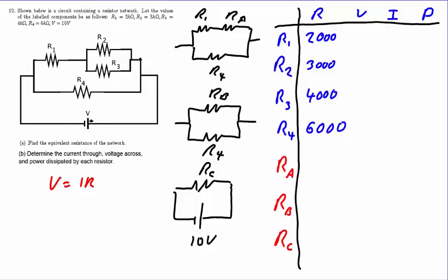If we put 2 4 kiloohm resistors in parallel, we'd get 2 as our answer. Our answer must be between 1.5 and 2 kiloohms, and if we use the appropriate formula, 1 over R total is 1 over R2 plus 1 over R3, we come up with the result 1,714 ohms, which is exactly as we would expect.